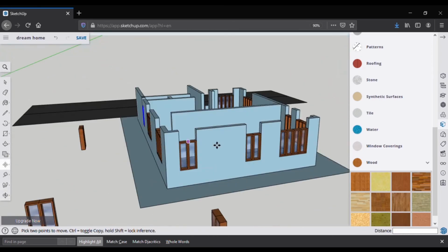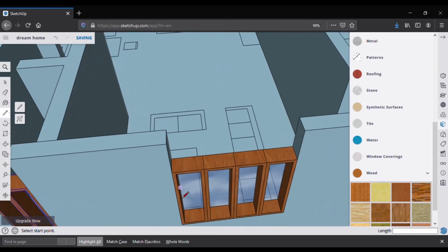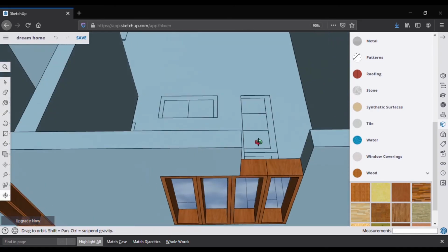There we go. We finished placing the windows. Now let's move forward and close the gap above the windows. For that, I'll just show a simple way. Just draw a line above the window like I've shown and use pull tool to extend it. As simple as it seems.